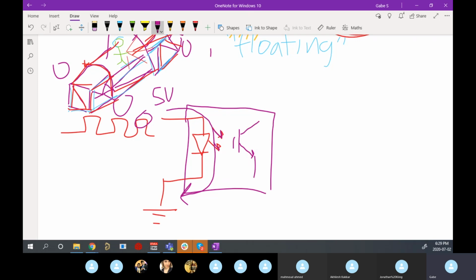But basically, it's almost like a little transistor. When you send a high, you send a 1, light will be emitted from this diode. The sensor will receive the light and close this switch. And then now you can send your 1 across, or whatever you want to do.